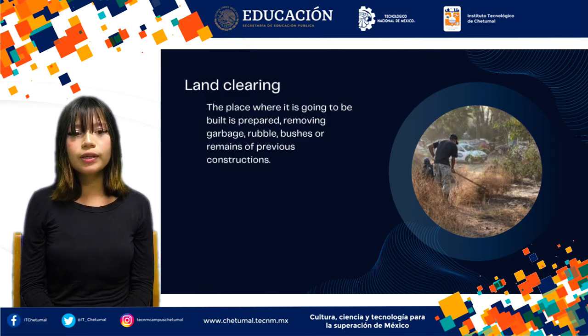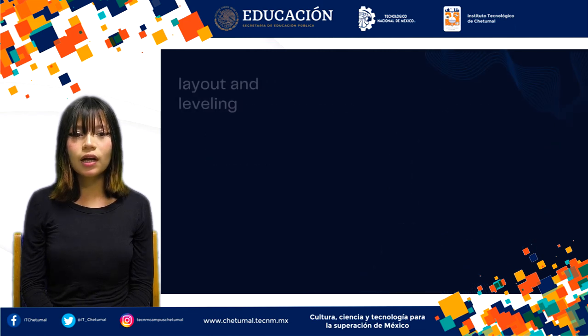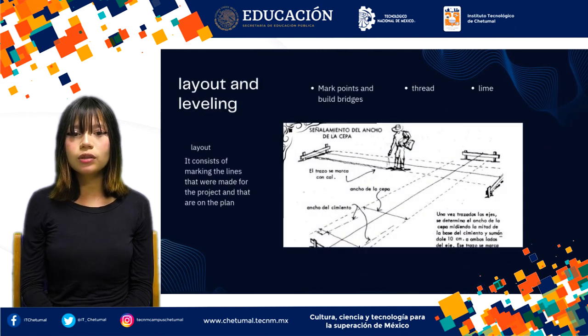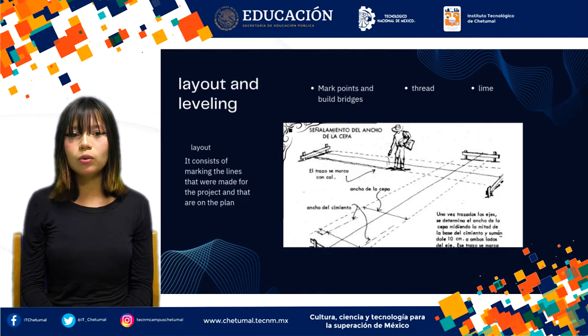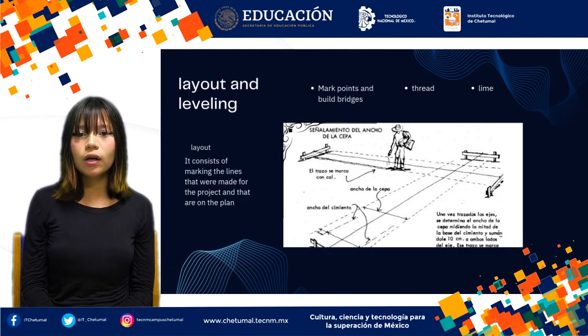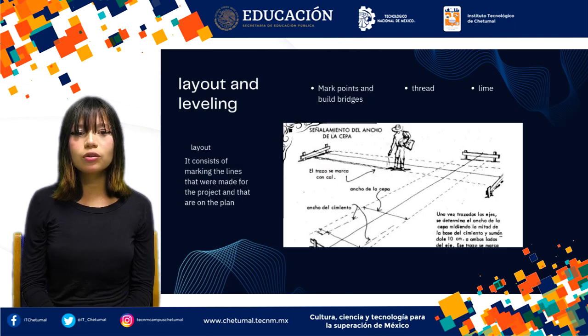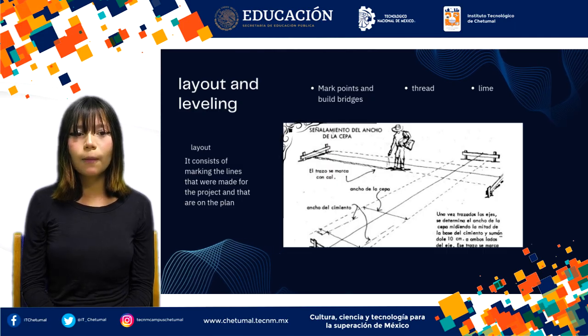Concrete curing. To reach its maximum strength, concrete must be properly cured, which involves keeping it moist for an extended period. This prevents the concrete from cracking and losing strength. There are different types of concrete, each designed to meet specific needs of a construction project. Plain concrete. This type of concrete does not include reinforcement and is used in elements that do not bear heavy loads, such as sidewalks or slabs. Its strength is lower compared to the other types.